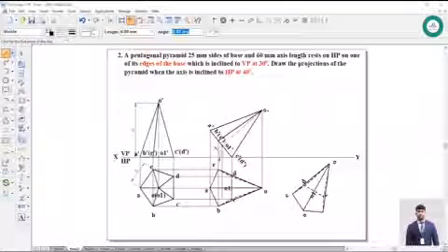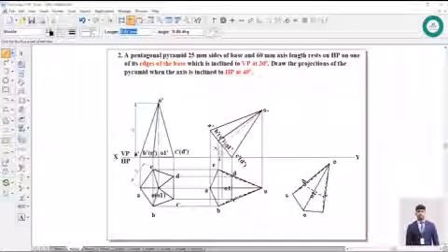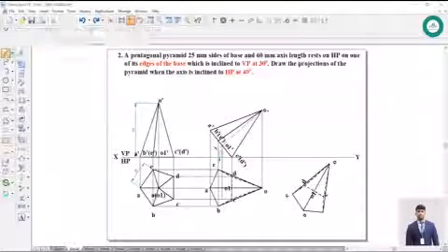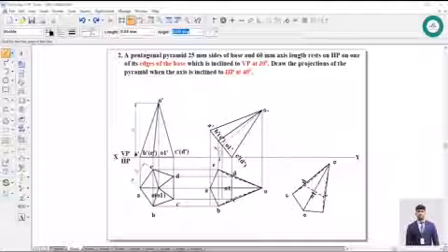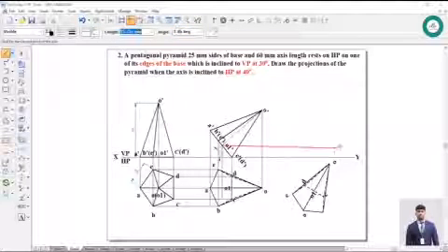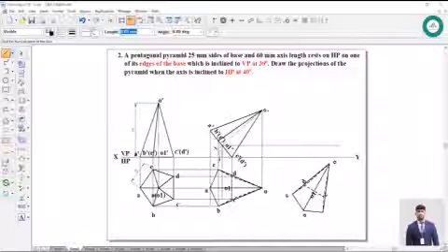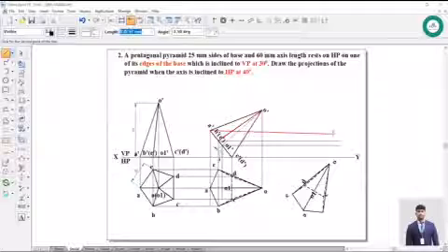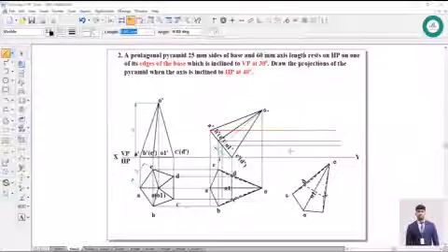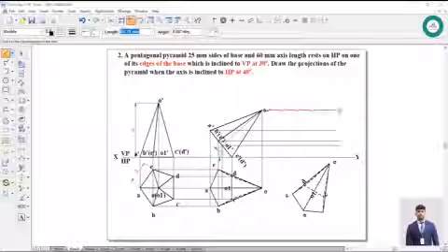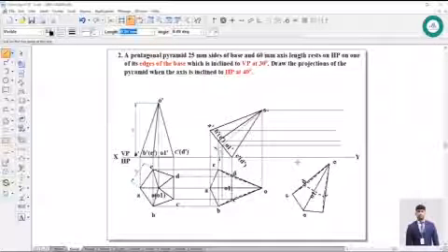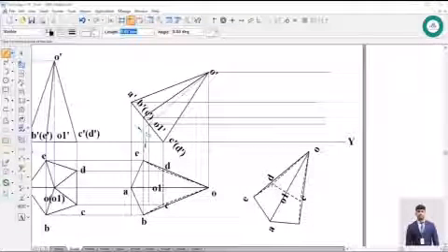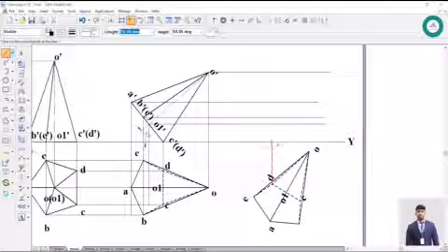Next, go to line command, take the least value, continuous, and from all the points start projecting to this right side. After projecting, let me zoom this area. We know that the resting edge always falls on the XY line.